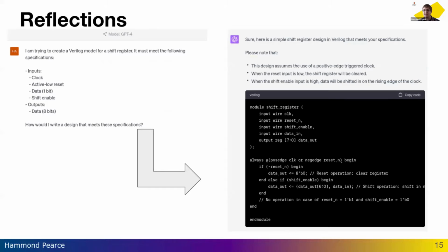And you would have seen that even with RapidGPT, right? Like that first block of code that it output when I first started, it actually had only really one thing wrong with it, which was that it didn't initialize the variable using an initial block. But you can make an argument that if you're writing code for an ASIC, you don't need those initial blocks, because ASICs actually need proper reset circuitry.